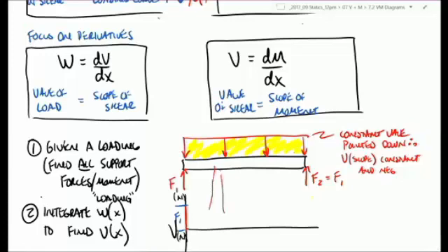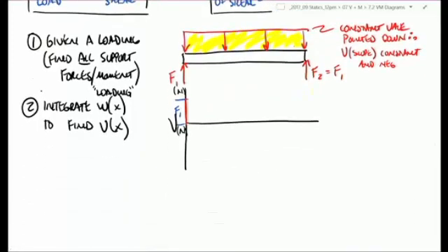All right, so that's going to be constant. I'm just trying to scroll my screen. There we go. If that's going to be constant and negative, it will look something like this. And then here at the far end, this concentrated load will push it back up, and I shouldn't have drawn that arrowhead there, technically. These are just graphs, not actual vector quantities. And so this would be the value of F2. We tend to shade these just so we can tell what's underneath the curve.